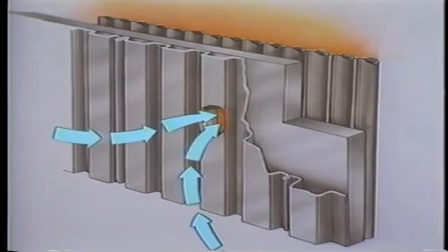Air leaking into the boiler through the casing can affect the combustion process, the operator's ability to maintain a proper boiler flame. If this is not the case, however, the operator can continue to operate the boiler until a shutdown can be scheduled. If combustion conditions cannot be properly maintained, the unit must be taken out of service immediately.